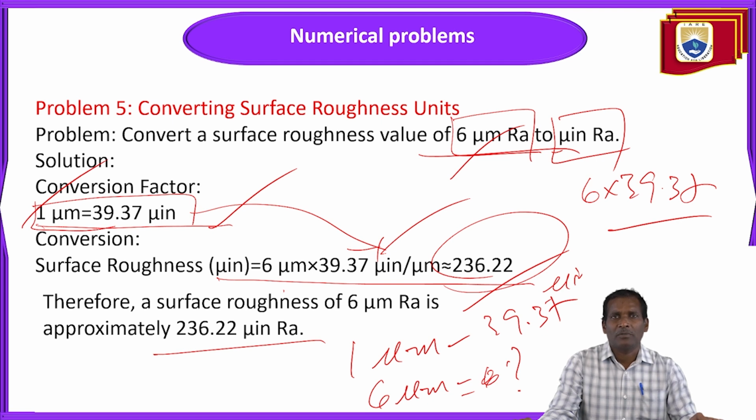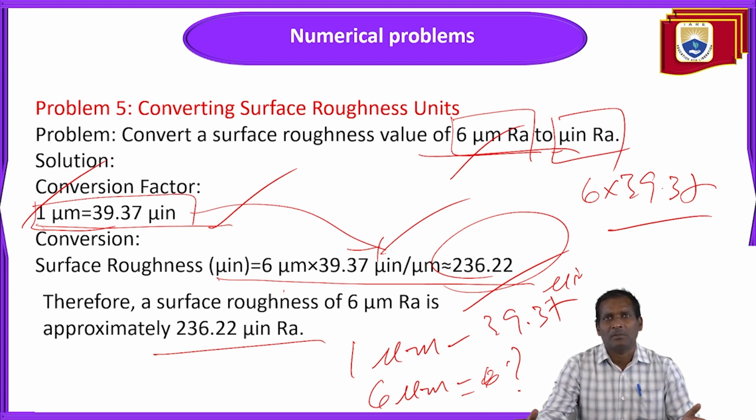Wear measurement methods: pin on disc is one method to calculate the wear of a particular surface. Before selecting the material, you first need to do the wear test, to see how much wear occurs for a particular load. By changing the load and the distance, the values may vary. Based on those values, after testing a number of samples, you can identify the optimal material for the particular application. That's why the pin on disc testing method is used to calculate friction and wear.